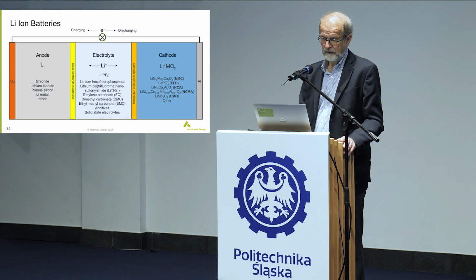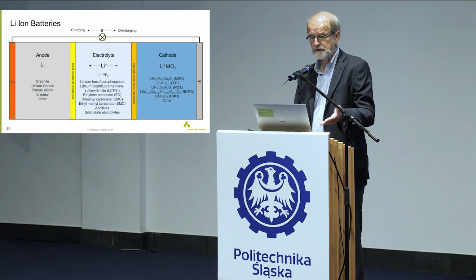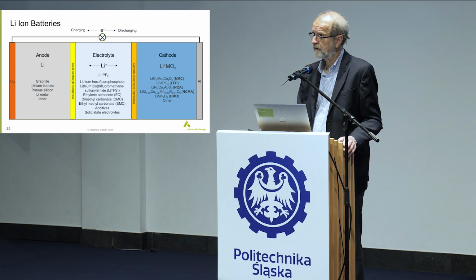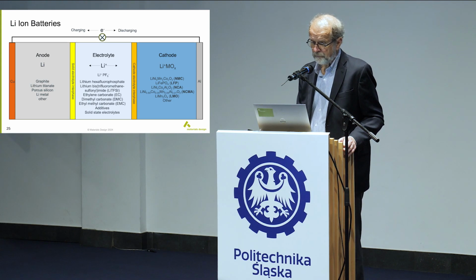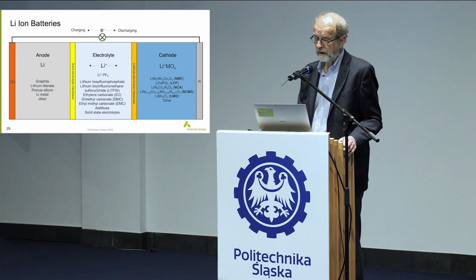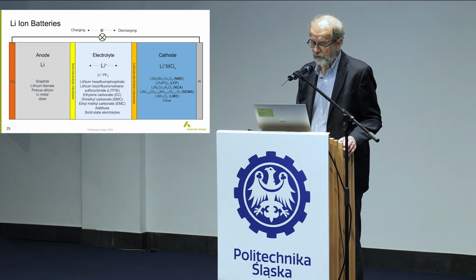So the lithium titanate, right now, the major batteries, for example in your cell phone, use graphite, lithium graphite. There are other solutions. Then the electrolyte: you have lithium hexafluorophosphate as a salt. So ionized lithium hexafluorophosphate is your ionic carrier in the electrolyte.